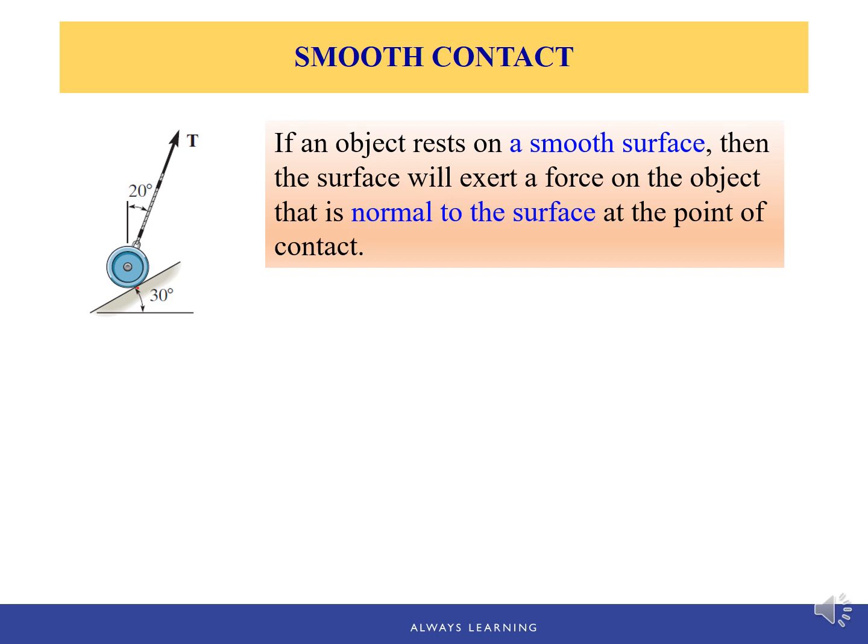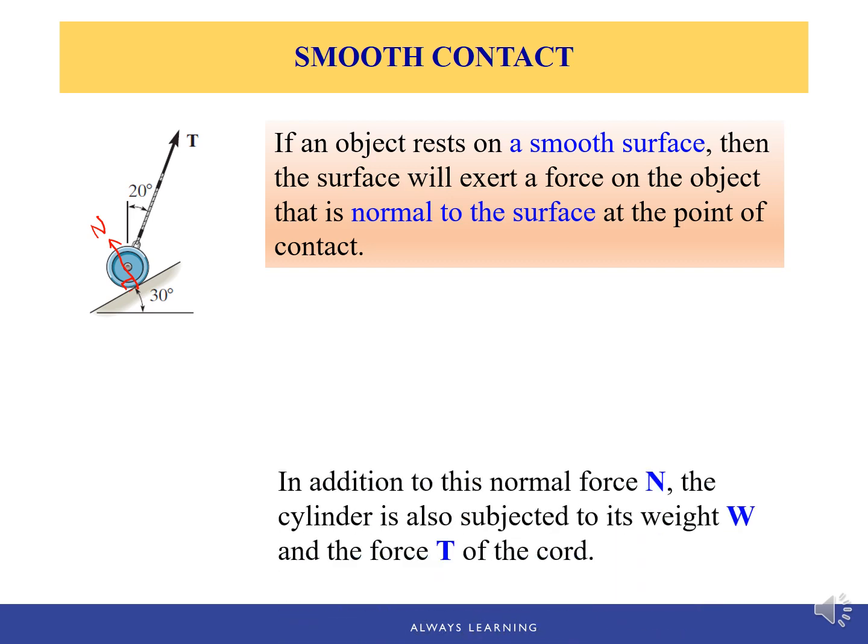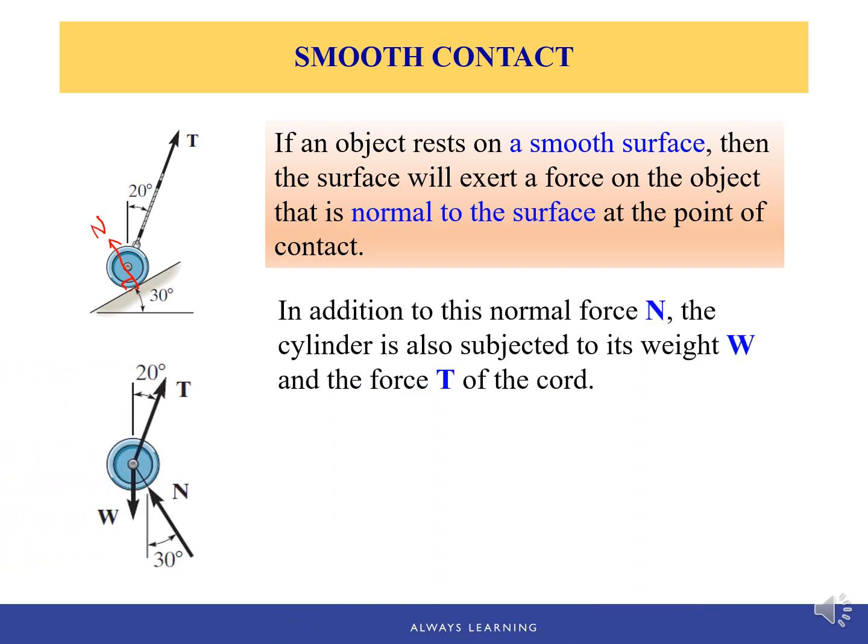The support reaction will be applied at or through this contact point, and it's perpendicular to the smooth surface, which means it's going up in this direction. We usually call this the normal force N, and it's perpendicular to the smooth contact surface.